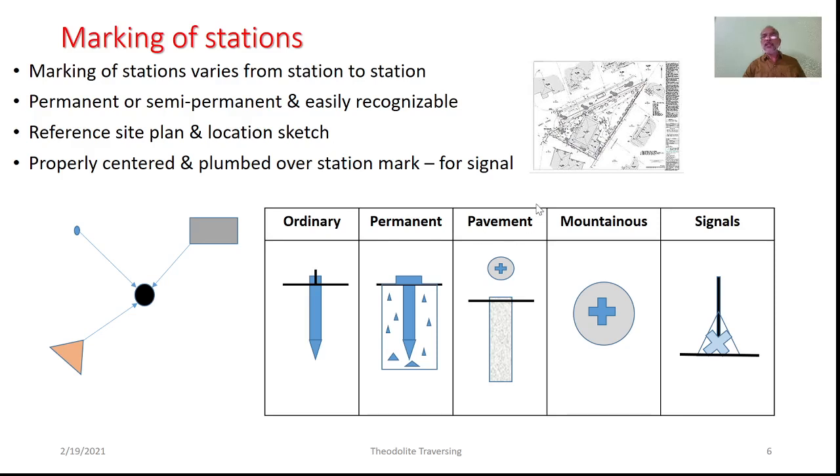As well, especially for the signals, the way you see here, this particular rod is placed above the station marking. So here, as one is expected to sight this vertical stem from very long sides, we have to be very cautious to see that this particular vertical portion will be lying exactly above the station under consideration. Say, for example, if we are dealing with triangulation networks, trilateration networks, at that time this kind of precaution is very much necessary.